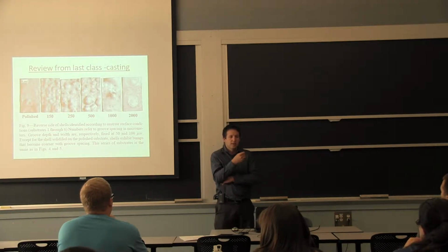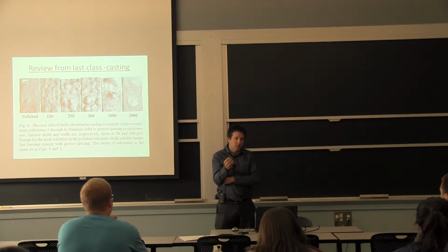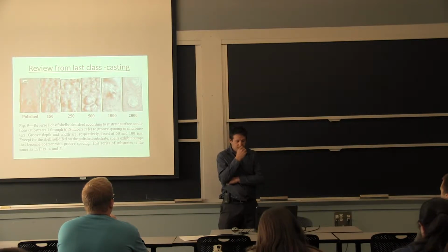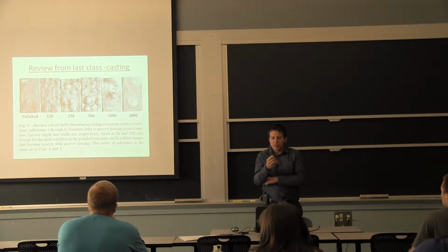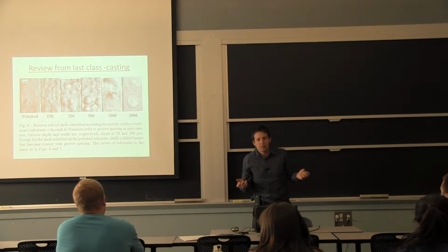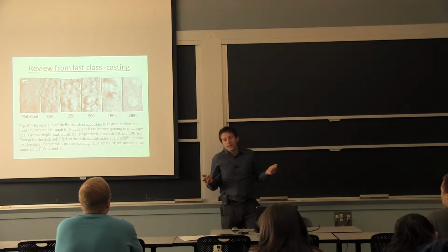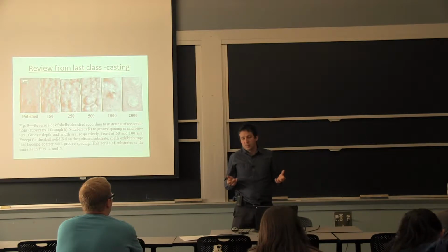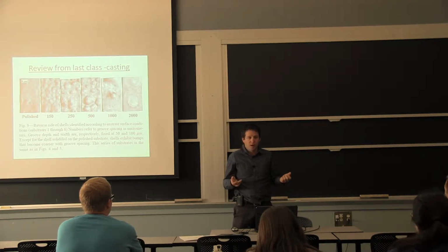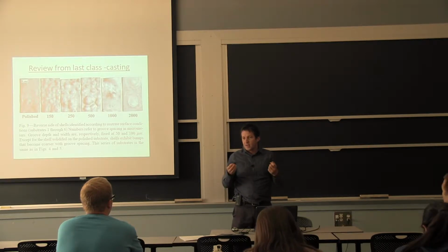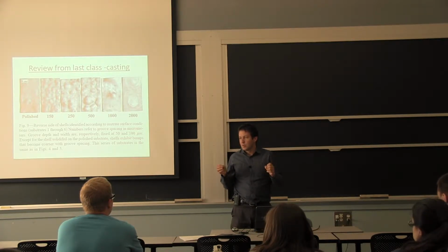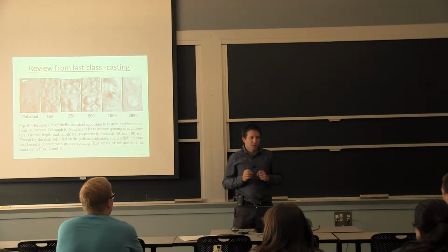So it takes some time to start the crystals, and then from the time you start it, the crystal is going to grow. It's not instantaneous, and it will essentially start the solidification at surfaces, and that comes across a lot in polymers. If you are solidifying polymers, semi-crystalline polymers like polyethylene, polypropylene, you can add particles that will act as nucleation sites, and that's a little bit how you distribute and control how many nucleation sites you're going to have.